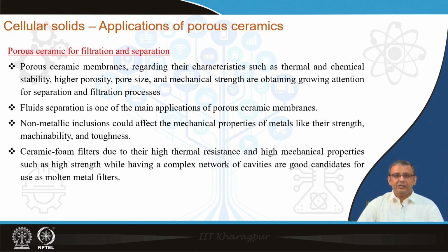So, in those applications, to remove those non-metallic inclusions, the liquid metal can be passed through a ceramic foam filter. These are typically called ceramic foam filters, and properties like the high porosity, the high temperature resistance, and the corrosion resistance of the porous ceramics can play a very good role over here.